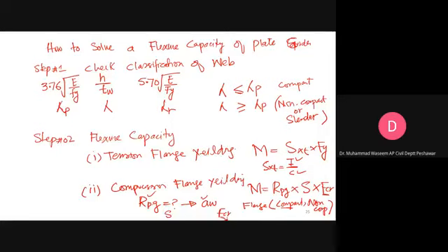So once you are done with the calculation, you have to see whichever is giving you the least value of bending moment. So that will be your flexural strength. And the one third limit state which I have not mentioned here is the LTB. Yes, I know it is difficult. It is difficult to absorb it, but I have tried to summarize all the things on this slide.